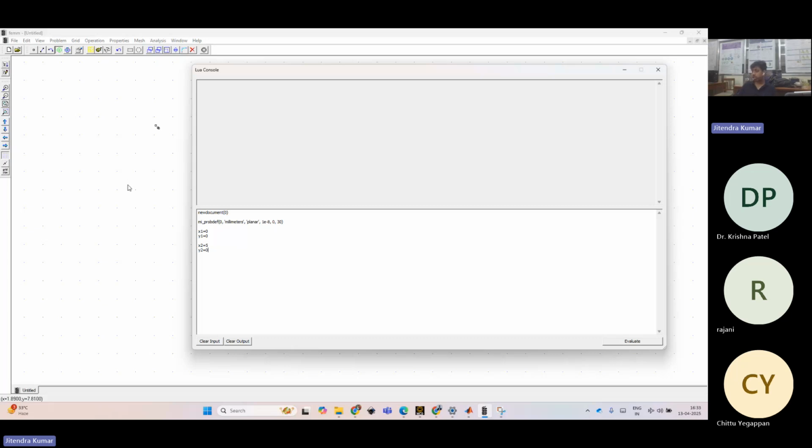Adding a node is very critical here because that will define everything. From a node, you could connect to anywhere. So to create a node here, there is a code for that: mi_addnode on the first point, which was x1, y1. Okay, we have created a node here for x1, y1.